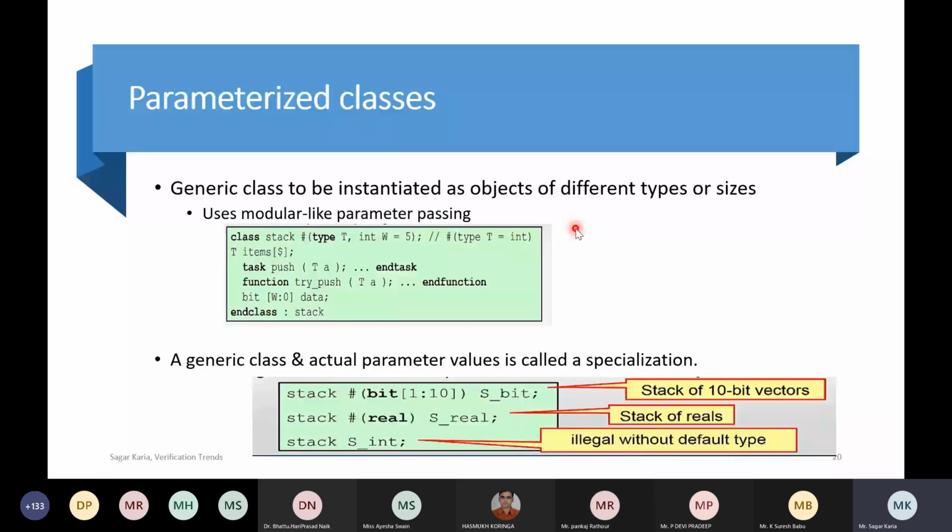Sir? Yes? Sir, as you mentioned, reusable test bench. Yes. What is the difference between Verilog and SystemVerilog there? So I explained in the first, in Verilog you write the test bench in a module, right? Because there is no class concept in Verilog. Yes, sir. With SystemVerilog there is a class concept, and as I showed in the first slide, that is why OOP is important for creating any reusable environment. Forget about the test bench, any reusable environment.